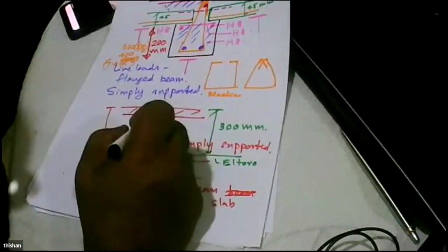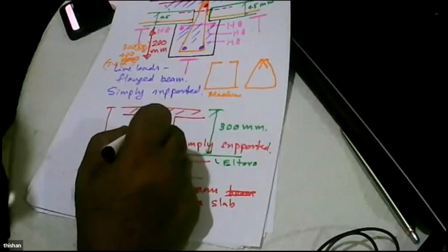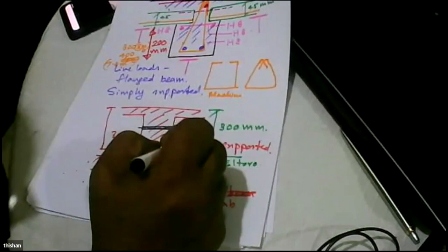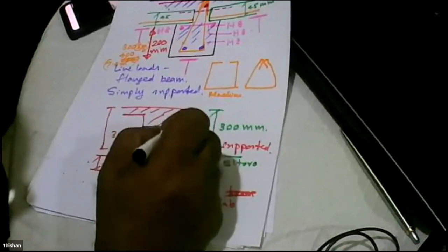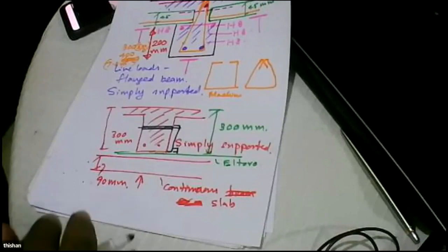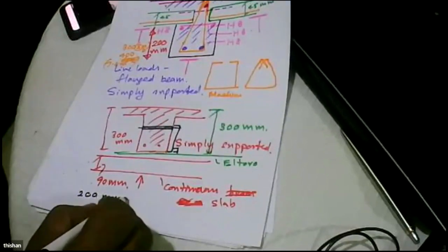Not difficult. Because when you are casting, there will be conduits here to provide the tie bolts. Using the same tie bolt that we use for casting the beam, we can fix the support structure of the ceiling. So the overall thickness of the slab will be 300, whereas with finishers, any other slab will come to about 200 millimeters.